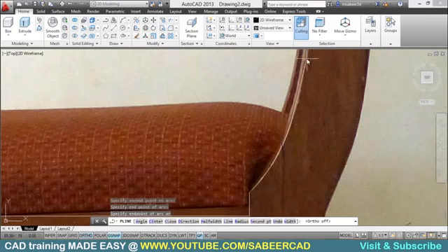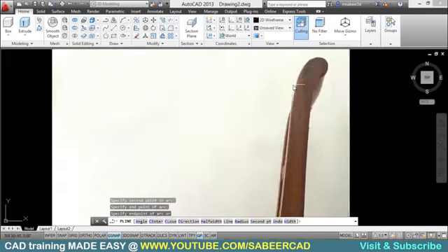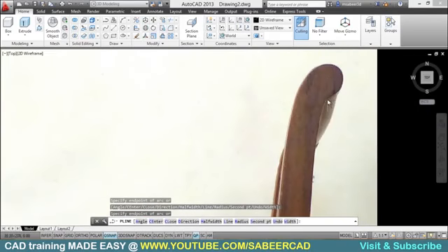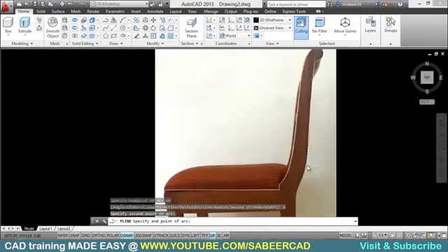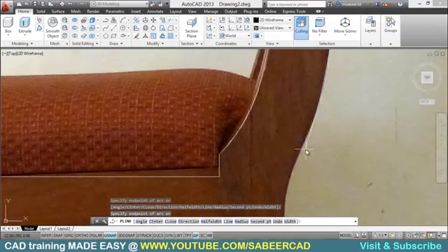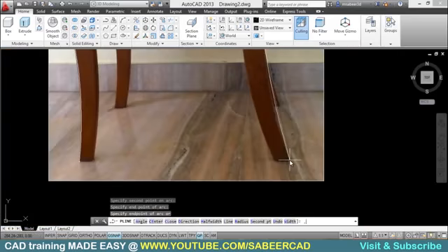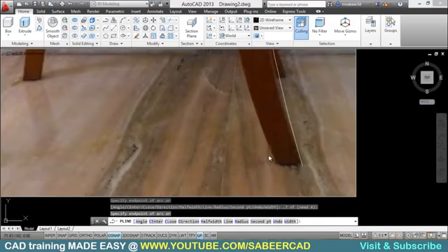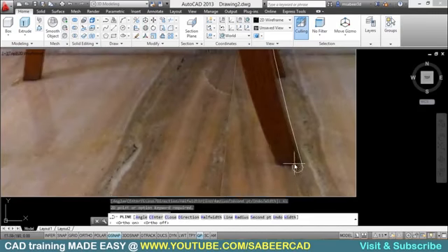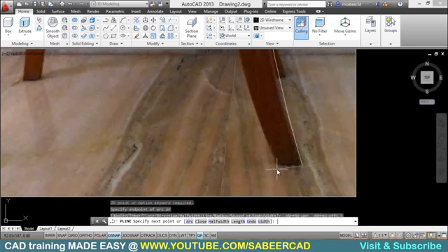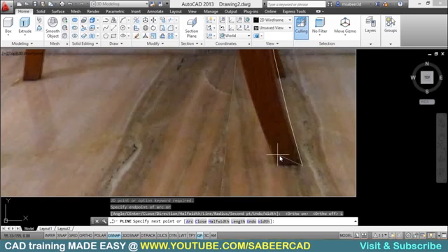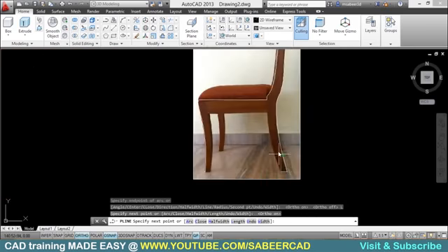Now I'll just fast forward this because the procedure is same. Polyline, arc, second point, then go to line if it's a linear segment. While picking the bottom point, I'll make use of point filters. So I'll give .y off, end of the bottom point on the left side. So I'll select that, and .x can be picked from there. I've used point filters because both the bottom points should be along the same horizontal line.